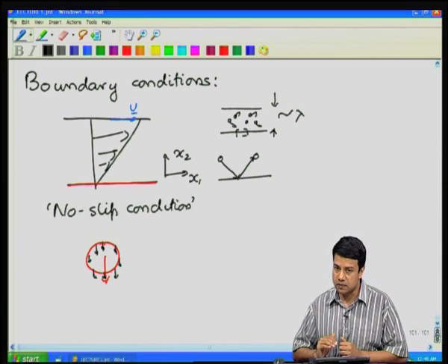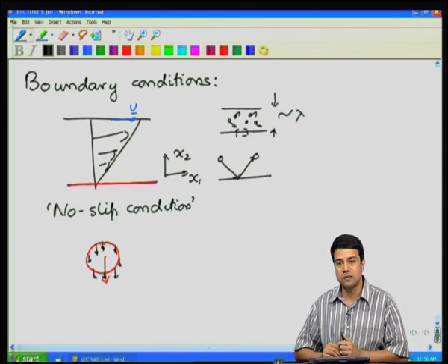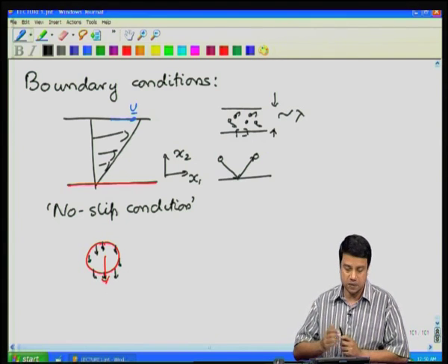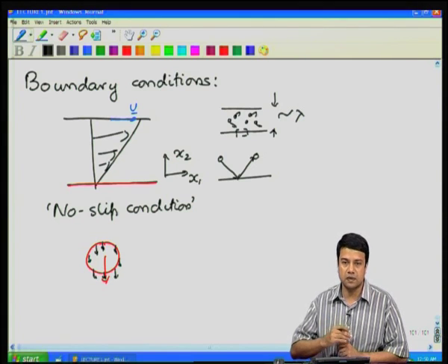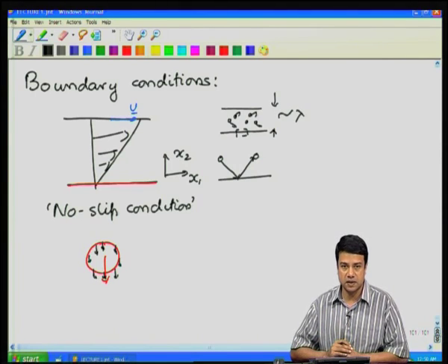When you enforce that the temperature at the surface is equal to the temperature of the fluid, there is no further necessity to say anything about the flux. You just require that the temperature at the boundaries has to be equal. Similarly here, when you are dealing with solid surfaces, you require that the velocity vector at the surface is equal to the velocity vector of the surface itself.